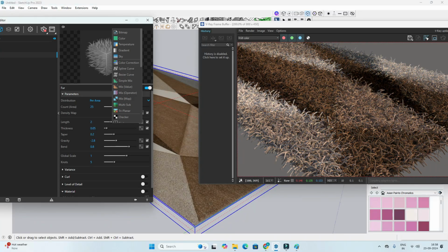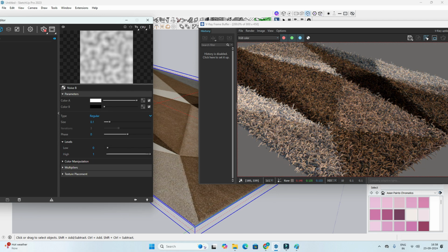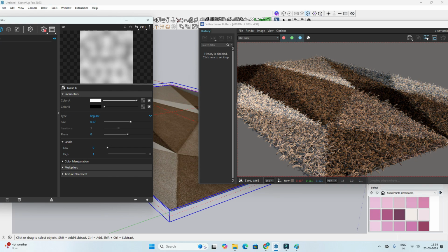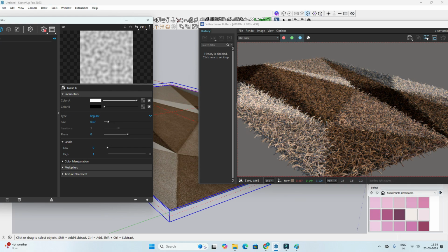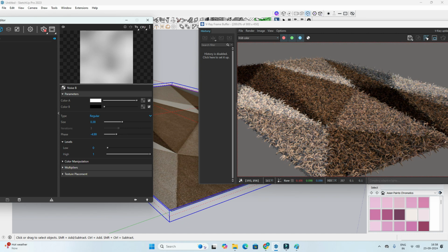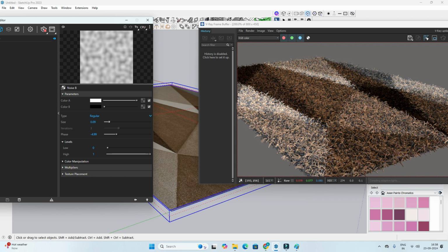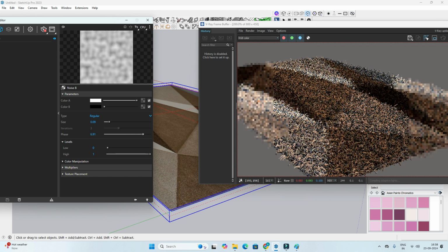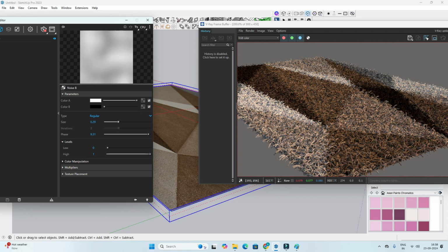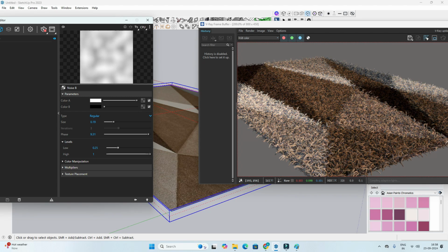In the length option I'm selecting some noise modifier. See, we have an option of noise A or noise B. I'm going with noise B here. After going to noise B, here we have to increase the size of that. See, when I keep on increasing this one or reducing that like this, and the phases also, I'm going to first reduce this and check the black and white. If I keep on going here, I'm getting more black colors, so a combination of black and white now, and give a lower power, sorry, reduce the height now.